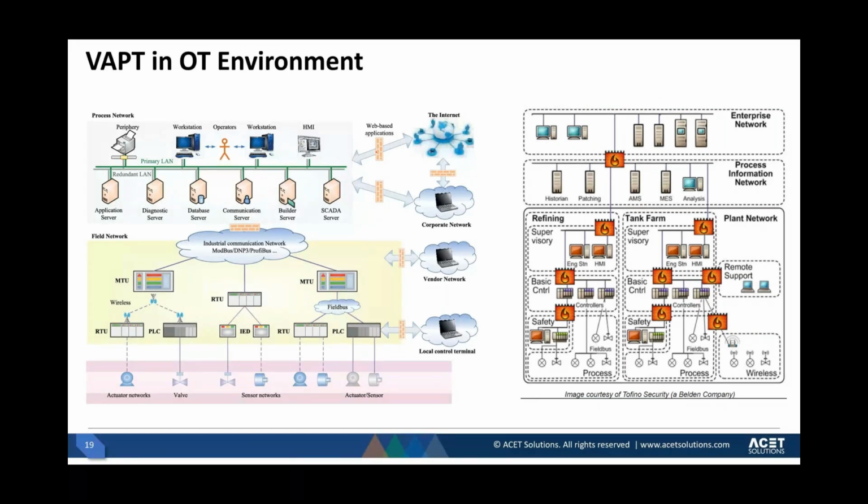But in a lot of these cases, I'd reiterate that I've seen many pen test reports, and in most cases, when the pen testing is done in the OT environment, the report is focusing more on the updates are missing here, and the patches are missing here, and the SNMP port is open over here, and the FTP port is open over here, which is good. But you could figure that out from a comprehensive vulnerability assessment.